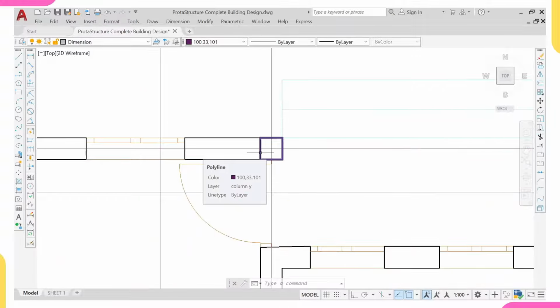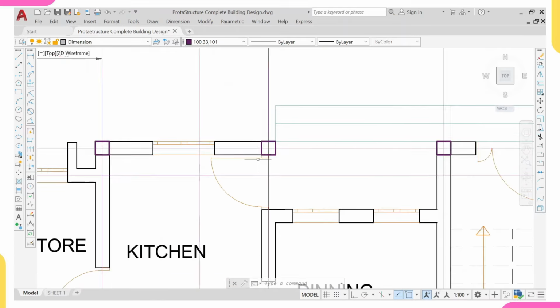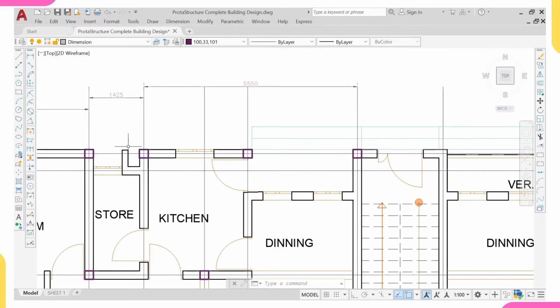Don't forget again, if you remove this column in your design, you might be having 3y16. Leave it, it is okay. If the client should complain that he's having 3y16 but other projects are 2y16, explain to him. He doesn't know. Most of those projects, maybe they're having a column here and a column here and also a column here. If you have a column here, here, and here, your work being 2y16 is a must. But if you remove this, that means the probability of you having 3y16 has increased. Yeah, here might be 3y16, but even though it is 3y16, you are still saving cost.